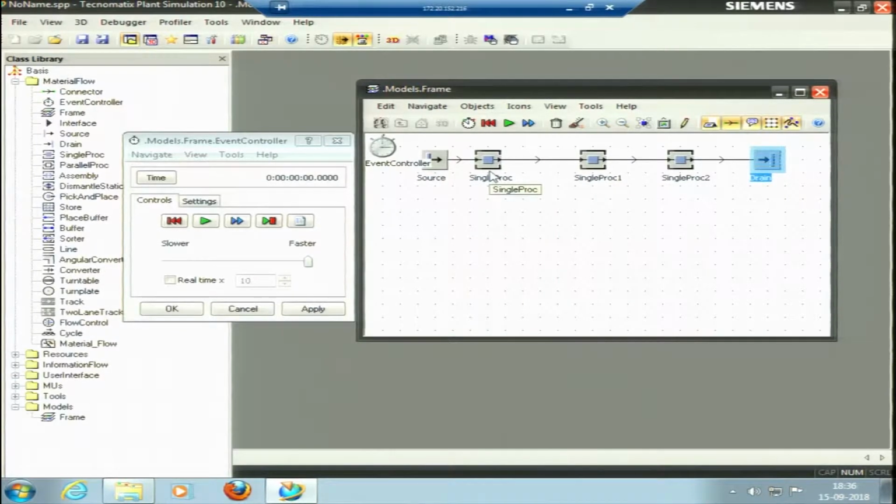If we talk about plant layout, this is work study: what is the minimum space that has to be kept? In manufacturing, other than the width of the machine, the space between two machines is generally kept from 0.8 meter to even more than that, so that the workers can move in between. So, this is a space in between.